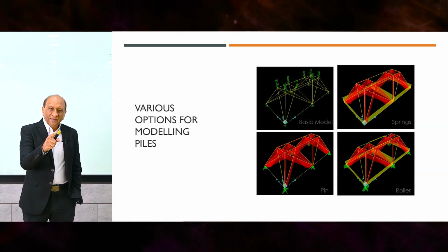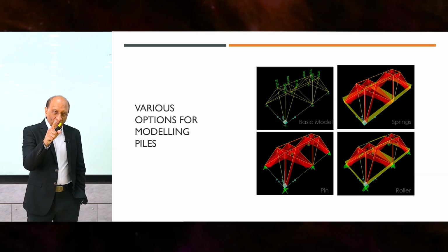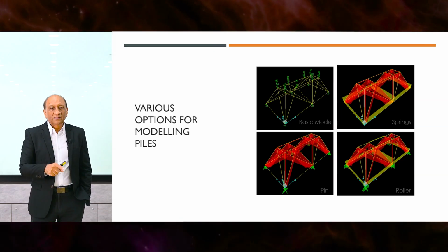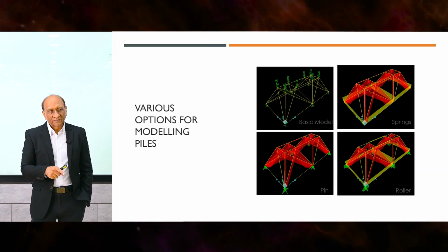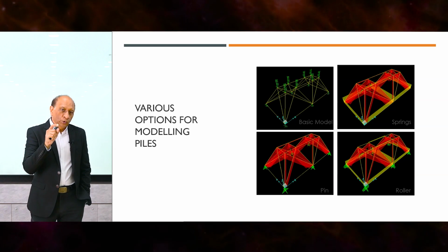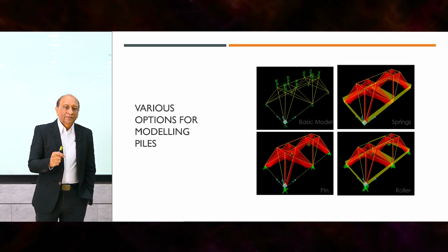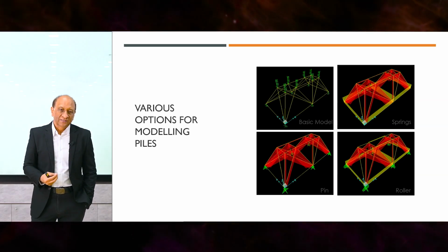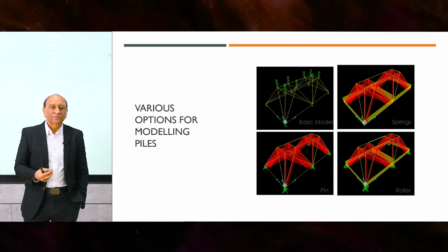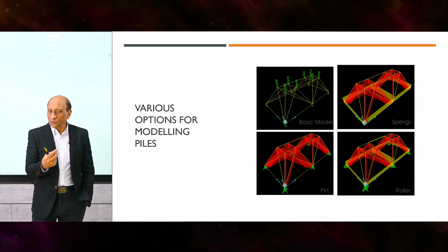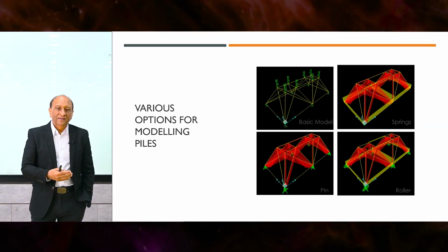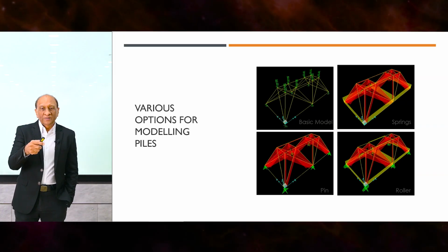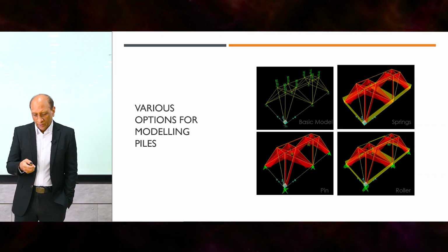It's important to see that the model below, the one just below the loading, is using pin support. And you can see 0 tension. There are no ties here. That means if you replace the piles by pin supports on all locations, you will not get any tension because the supports will just absorb the strut forces. And that is so wrong because you will not have any reinforcement in the pile cap then. So we need to make sure that we use pin roller or spring supports appropriately.